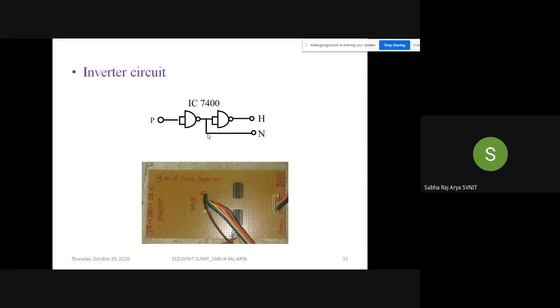The DC link is going to short circuit through this leg. If a device change takes place in the same leg, the upper IGBT is conducting, that one is going to turn off and the lower IGBT is going to turn on. Between that, we need some delay time. How much? 2 to 5 microseconds, maybe near to this, maybe somewhat higher, no problem. If we take a higher value, then your PWM pulses are going to be missed and performance is going to deteriorate. That is a disadvantage.